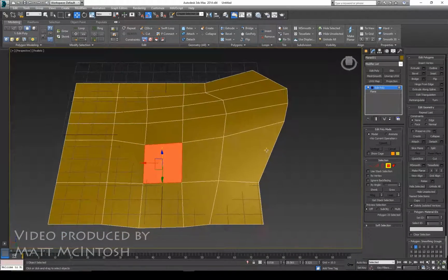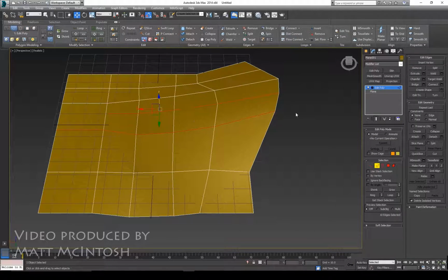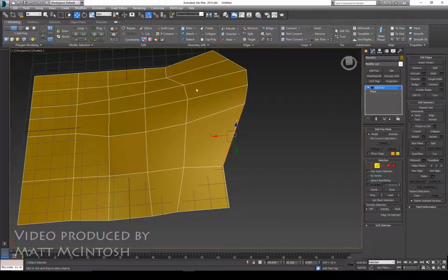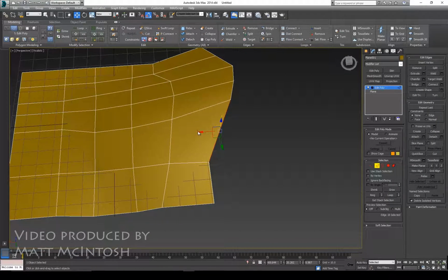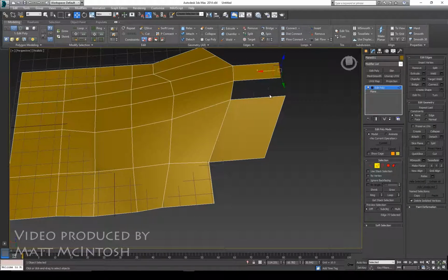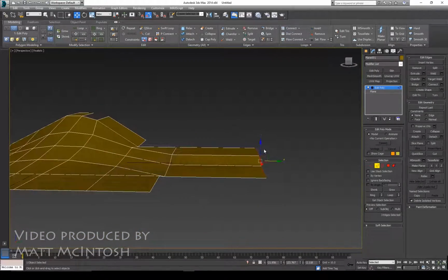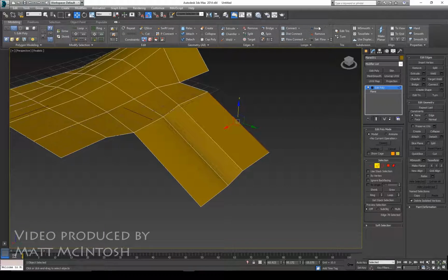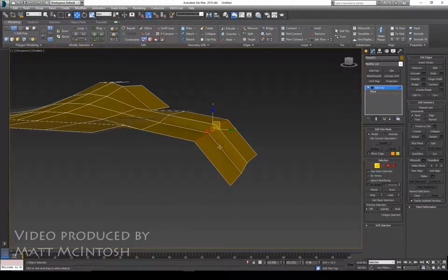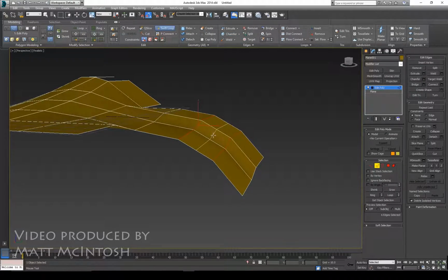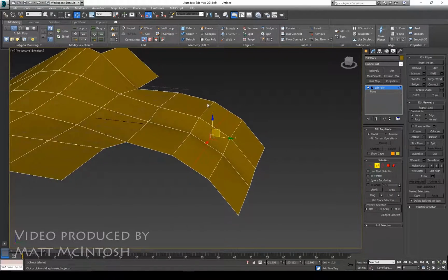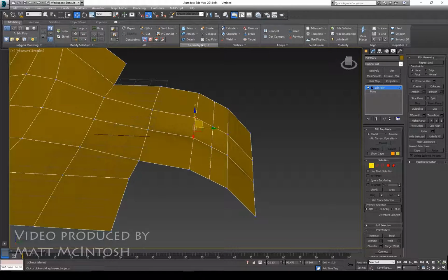Okay, so one other vital tool that you would need if you're creating things is the ability to actually create an edge. Now you could potentially use the Extrude tool, but what I'm going to use is just pressing the Shift key and dragging out, and this allows you to just create new edges, and you can do multiple ones at the same time. So example here, I just select 3 edges, there we go, I can create a row of edges, then maybe click the insert tool to add in some geometry. Maybe I want to use the chamfer tool to just even that out. Again, maybe I want to add in a swift loop, and then maybe I want to make use of the smoothing tool, the relax tool, to just even things out a little bit so that it's not quite as sharp on that edge there.